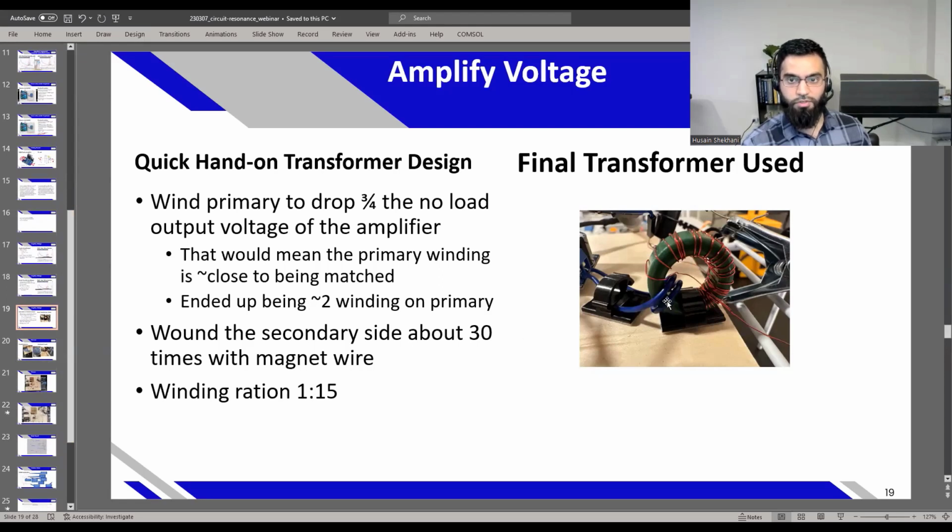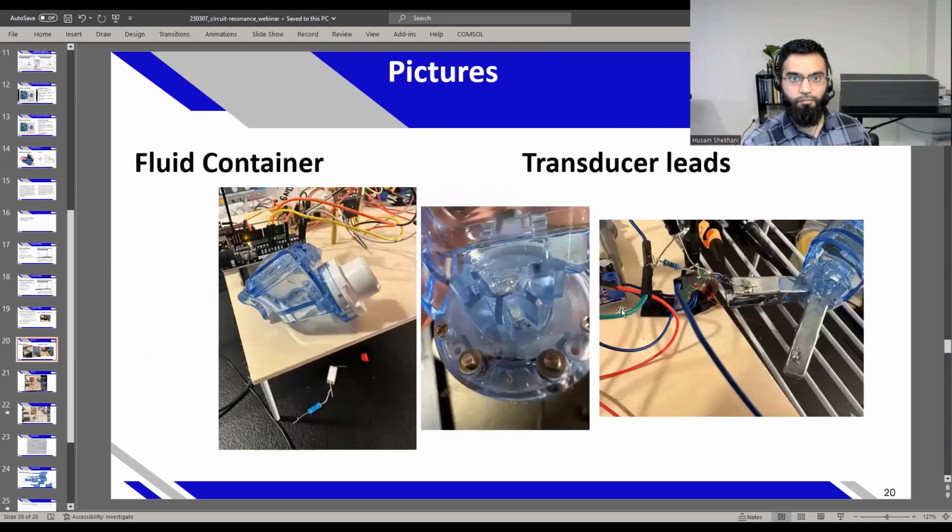I think I also bought this from Amazon. It just tends to be easier for me with the 2-day shipping. I don't have to pay for it. So yeah, this is about the size of a ring, and I'll give the inductance values later. The secondary side is about 30 windings, and you can also wind the secondary side with smaller gauge wire. It has less current, and it doesn't really matter for this frequency and these current levels, but you can do it. You can make the windings tighter and do things like that too.